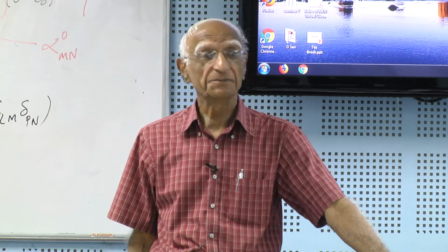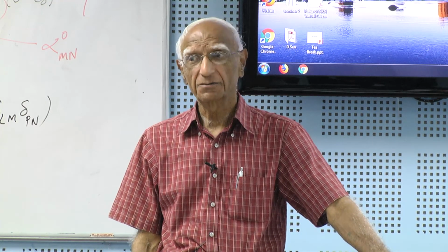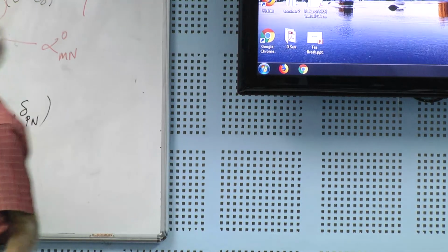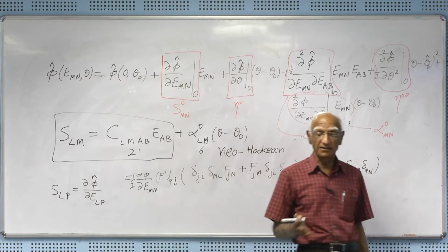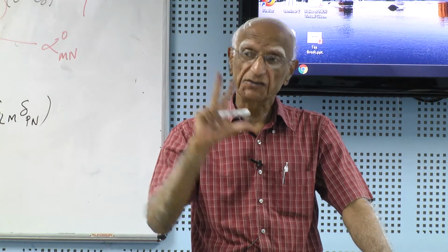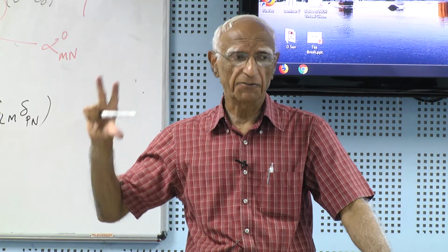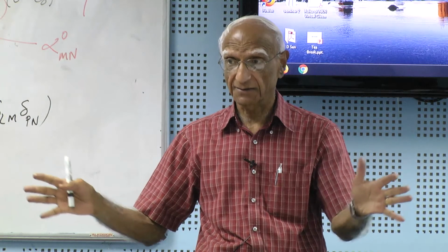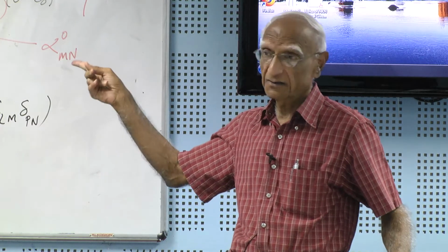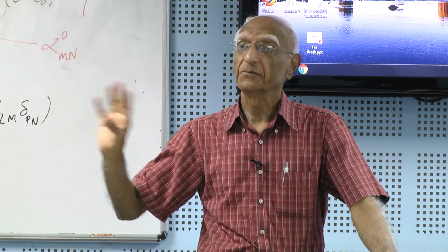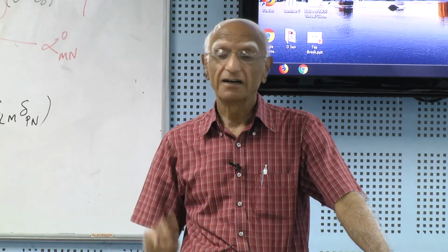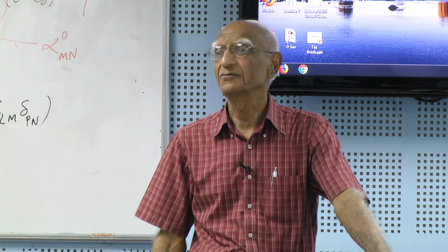So tomorrow I will show you that if you take an isotropic material and take different nonlinear relations, they are basically still a stress tensor that is a linear function of a strain tensor, not the same ones, because we have to satisfy material objectivity that we talked about, and also if I take isotropic, then I have to satisfy material symmetry condition.